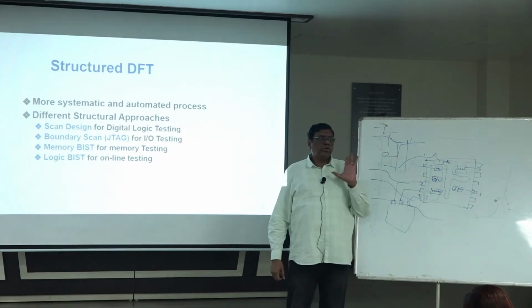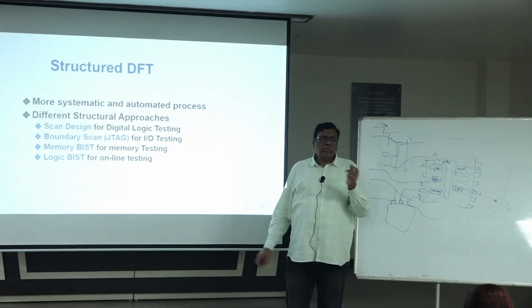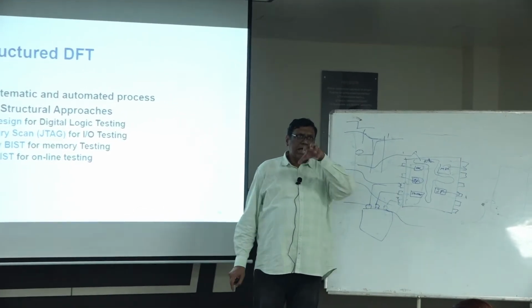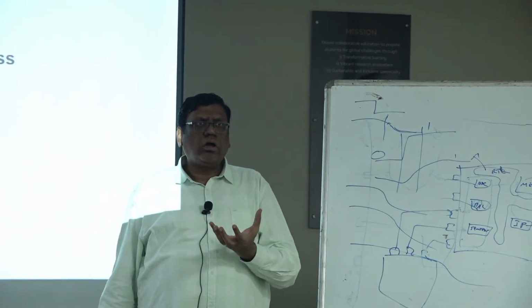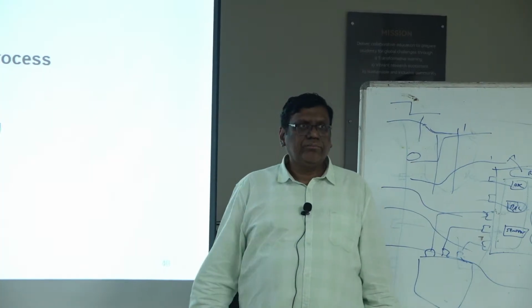Whatever board you study, maybe you are using so many boards, whatever board you use, you will have a JTAG pin. That's standardized, because they will have different ICs inside. IC to IC connectivity on the board, how will they verify? This is one of the techniques called boundary scan.